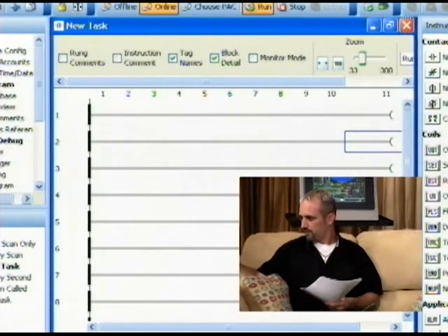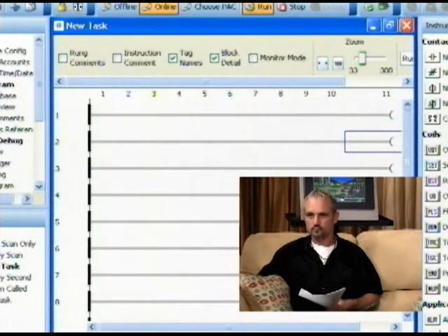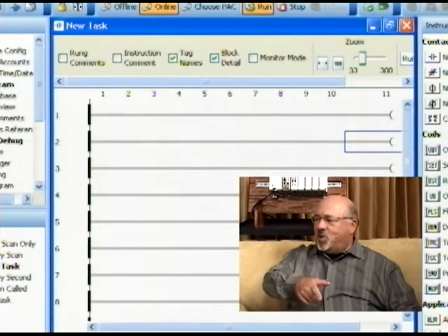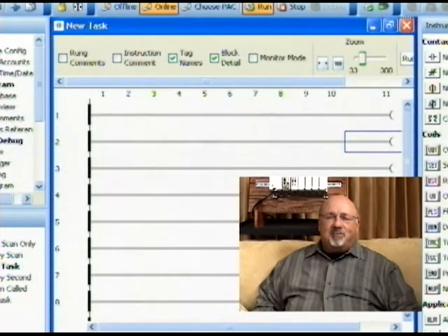It's so easy. Since we're on the PAC, we talked about the ports on the PAC, and jumping around a little bit here, the whole talk show today is in regards to Ethernet. Real quick, wanted to explain again on the Productivity 3000 CPU, we can do Ethernet for our communications, but we also use Ethernet for our local I/O expansion, so we can take from the base, from the CPU, and go to a remote slave unit with Ethernet cable again. And also I should mention on the PAC, since we talked about USB, we can also do local remote with USB type cabling.